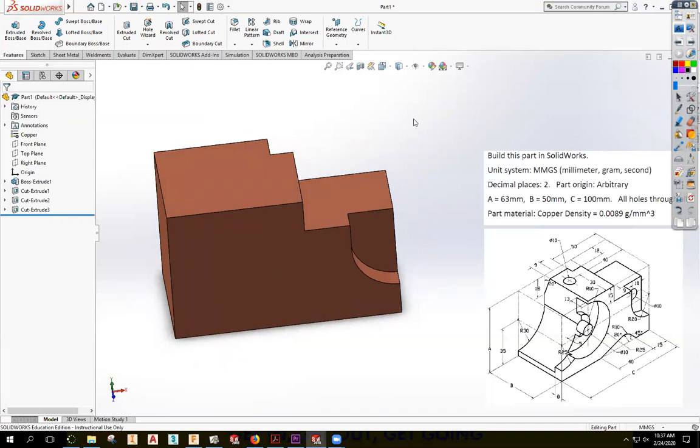Okay. Draw just what you need. In SolidWorks, if you don't have a closed profile, like that profile, I didn't have it closed, I could pick which direction.